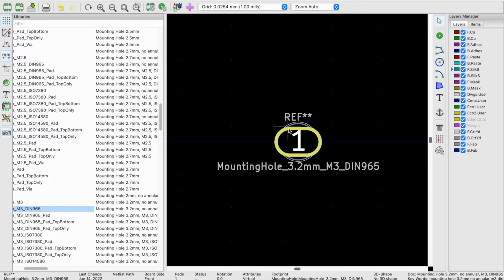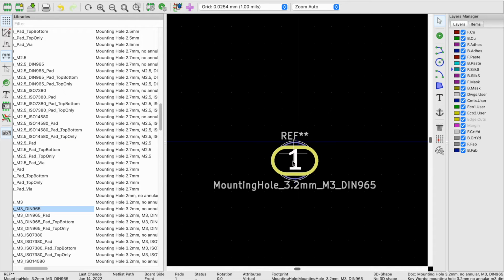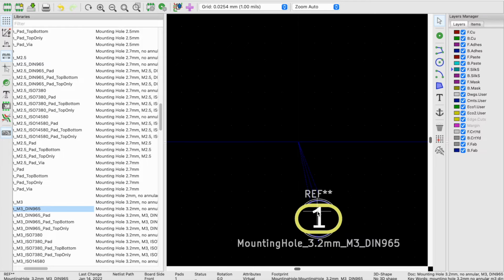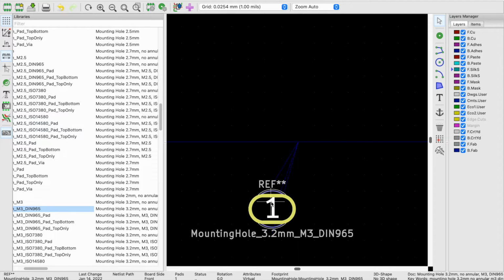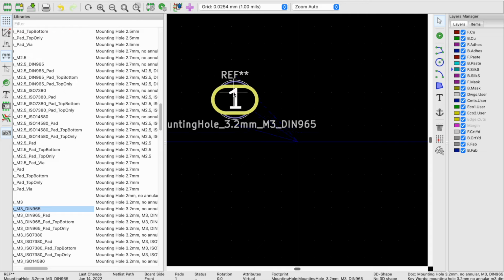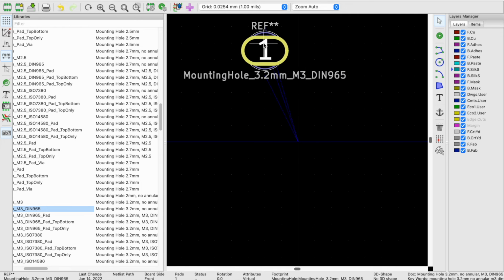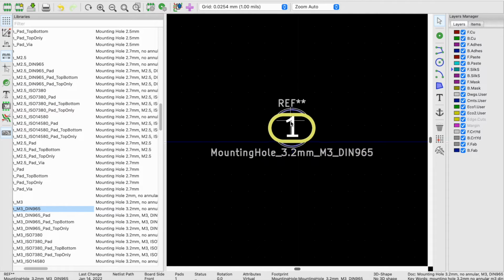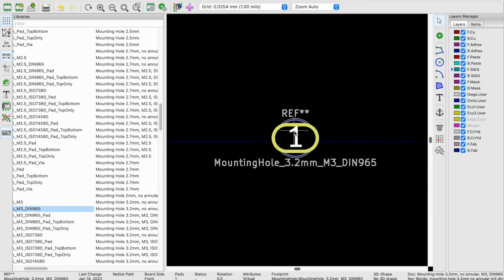I want to touch on the concept of anchor points here in PCBnew. This will become very important later when we go to actually place the mounting holes, because you want the holes to line up with the screw holes on your rails. This means you need them spaced correctly as well as placed in the right location on the panel so they sit right on top of the respective rail screw holes.